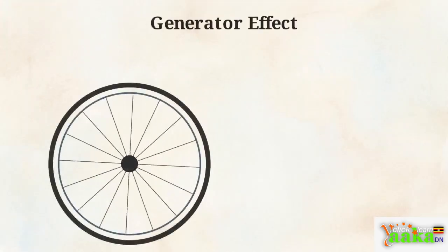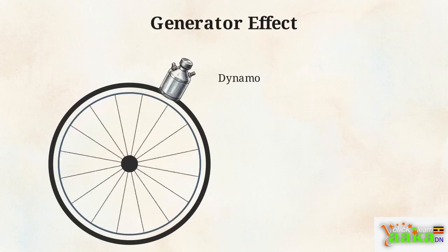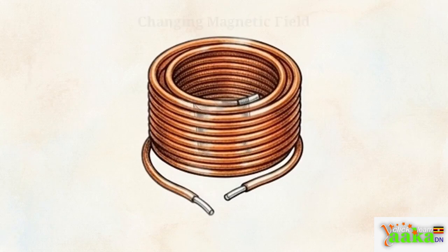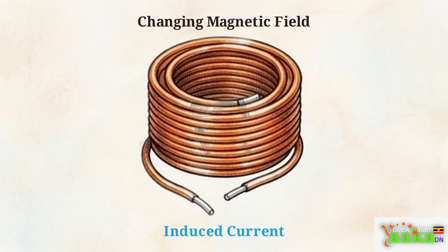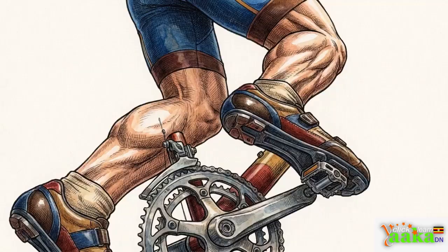We can also run this process in reverse through electromagnetic induction, sometimes called the generator effect. Here, we use physical motion to create an electric current, like in a bicycle dynamo. As the magnet spins inside the coil, the magnetic field constantly changes. This shifting magnetic flux physically drags the electrons along the wire, inducing an electrical current. You can feel this physics in action when using a bicycle dynamo. As you switch on more lights to draw more current, the pedals become noticeably harder to push.